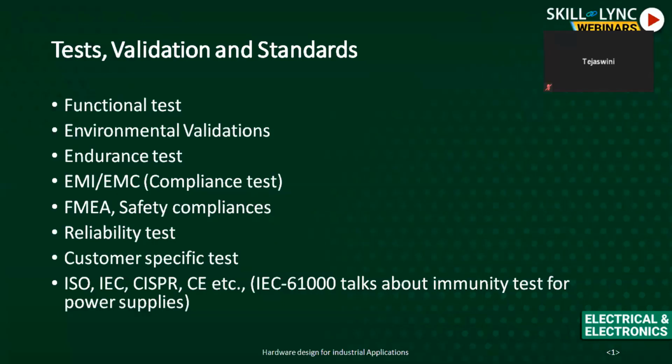Then the endurance test. Continuously, I'm going to make this GPIO high and give it some load. It should withstand normally around 1000 cycles, 1000 hours or so. This is the endurance test. Then the EMI and EMC compliance test.